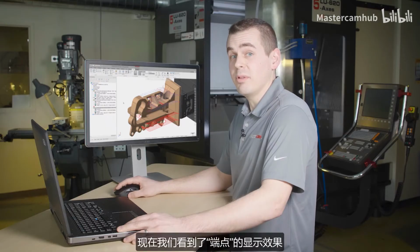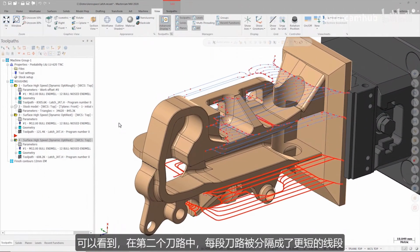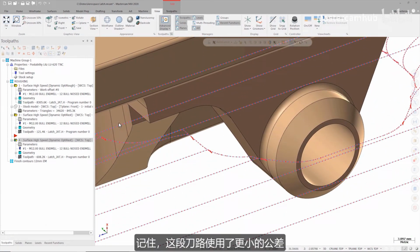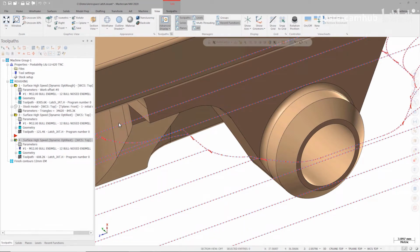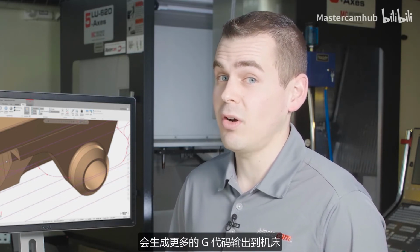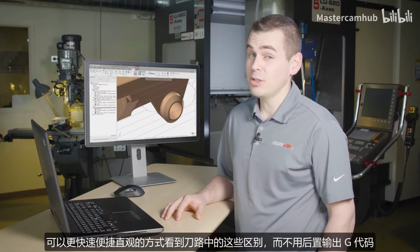Now that we have these endpoints displayed, we can start to get a feel for how much code we will have when posting out. If we look at the second toolpath, we can see that it's broken up into much smaller segments. Remember, this is the toolpath that was using a tighter tolerance and had arc filtering turned off. Tolerance and arc filter settings have a massive effect on toolpath output and calculation. By turning off the arc filter and tightening up my tolerances, I'm giving the machine far more code to handle. Thanks to Advanced Toolpath Display, I can examine these differences in a quick, easy, and visual way without having to post the code.